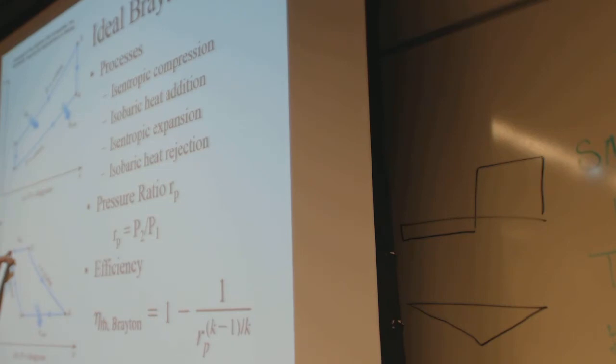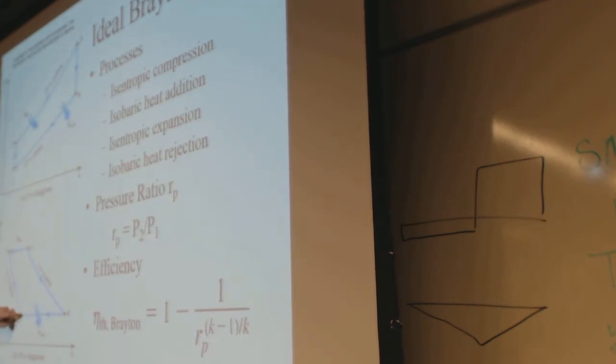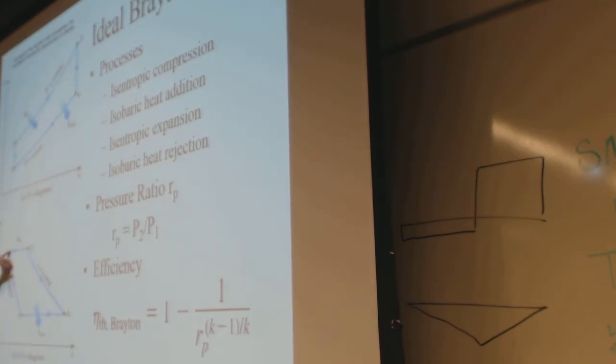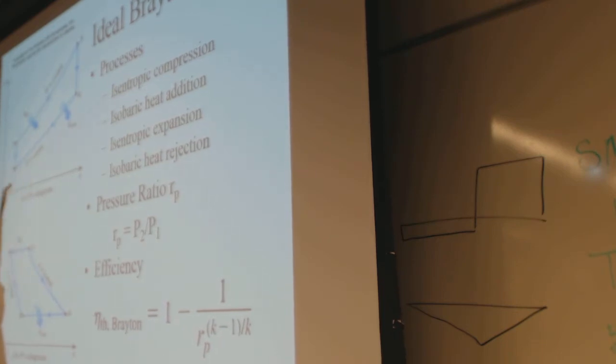So it comes up to the new pressure, and then you add heat, and it expands to a new temperature. In this case, the compression is isentropic, S equals constant, and we have an isentropic expansion through the turbine. Q in is going to jet up. The pressure is constant, but on the TS diagram, temperature-entropy, temperature rises, no doubt, you just put a bunch of fuel in it.